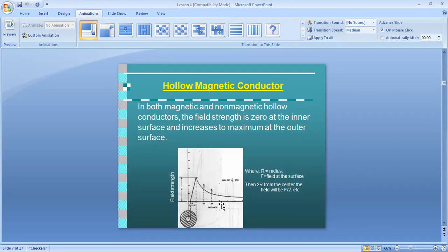That's why we have to keep our job close to the conductor. Suppose we have the ring, so how will we keep the ring here? We will keep the ring like this, right? And this is the conductor here at the center, and we are sending current through the conductor. Then lines of force are generated, and these lines of force will be induced in this part, and you will get a magnetic field. Okay, so this gap should be as small as possible.